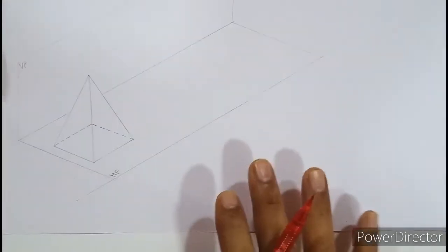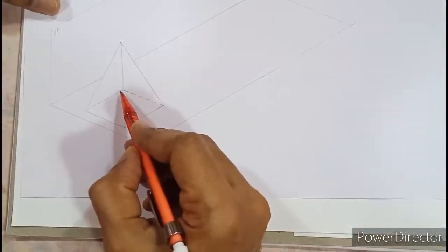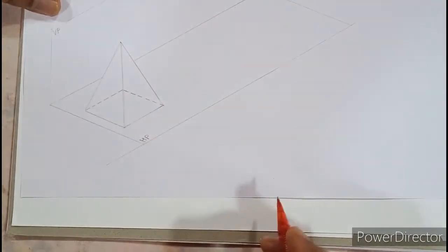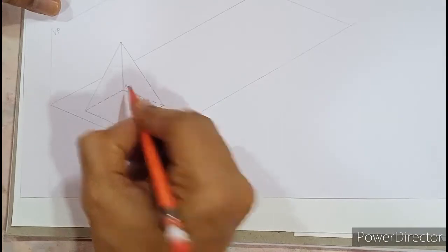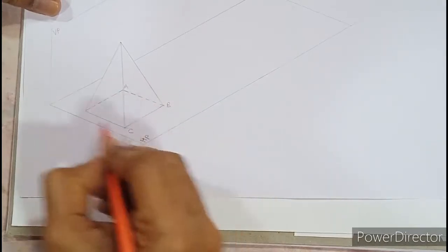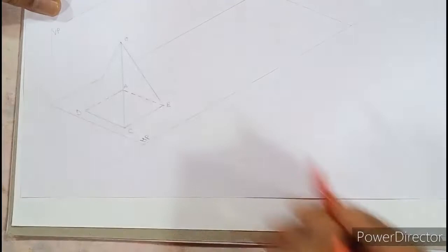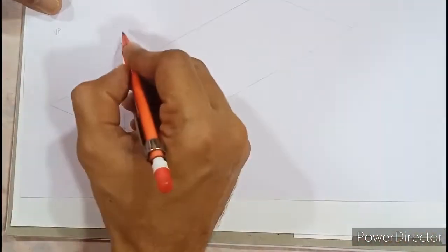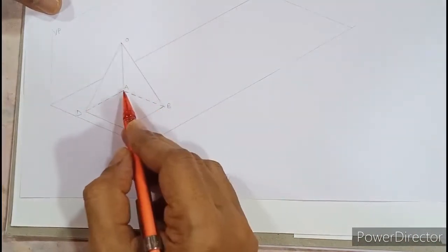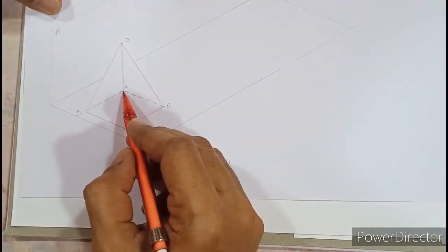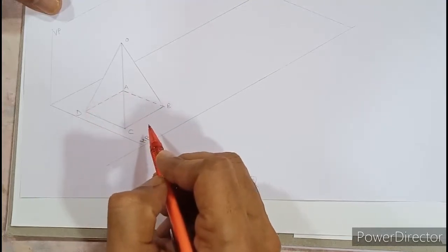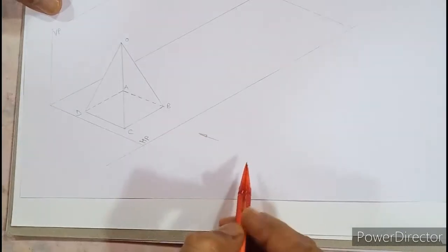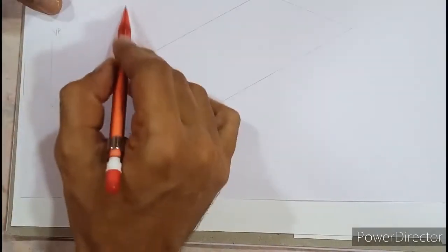So to begin with this numerical, this word problem, this is a square pyramid of side 40 and axis height is 70 mm. So if I take this corner as capital A, this is capital B, C, D and apex as O. So you should start with that view from where you can see the true shape of the base. So that is the top view. You can see ABCD. And we have seen in lines that top view should be named without dash and in small alphabets. And also there is a gap from here. So see, front view is from this side, right? So standing over here, you need to look in the top. So top view is from here.